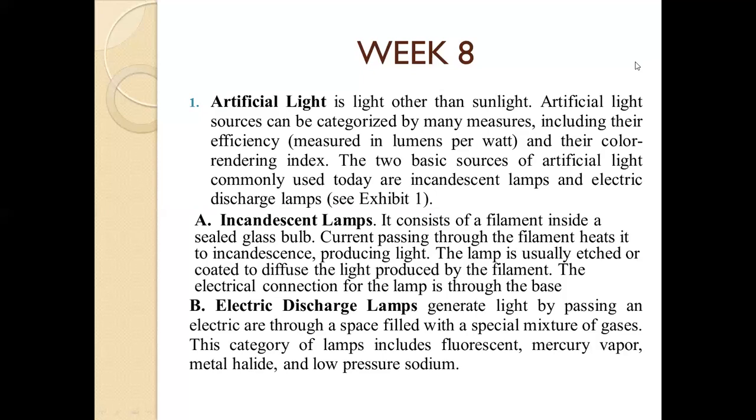Basically, these electric discharge lamps can't be operated directly from a power supply as can incandescent lamps. Therefore, electric discharge lamps require an additional piece of equipment, a ballast, that controls their starting and operation and acts as a current limiting device.